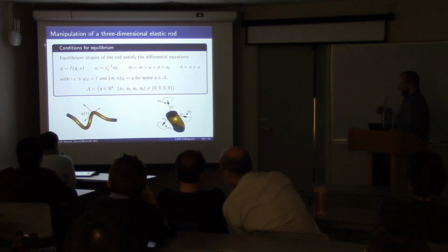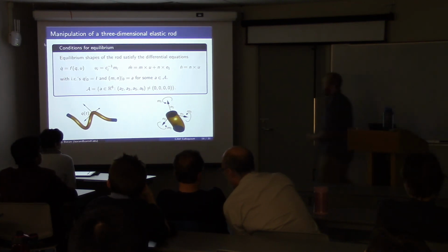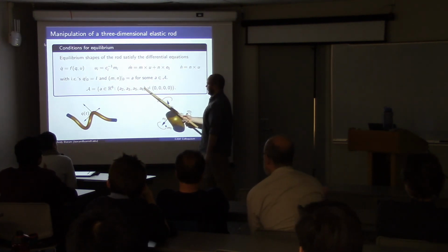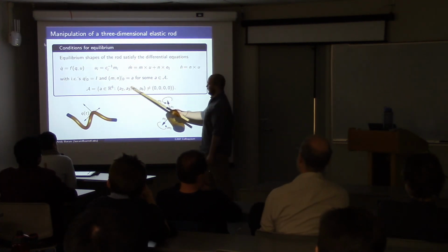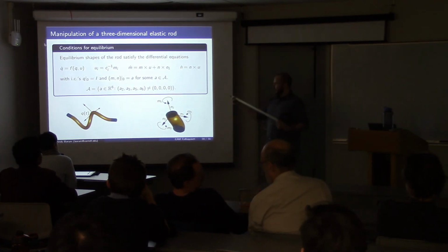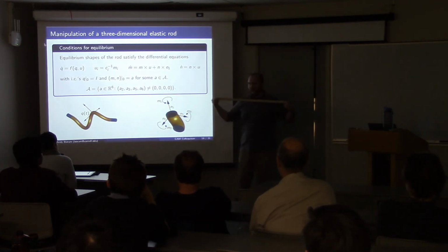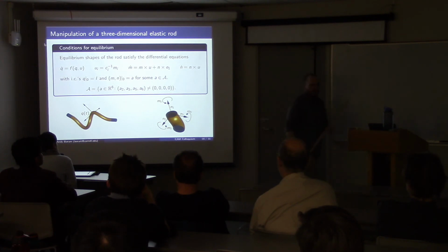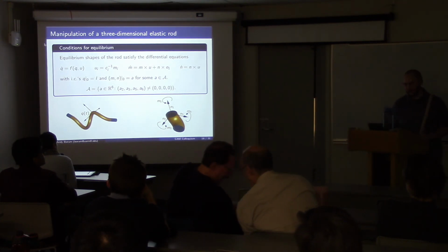And now the plane that we have to avoid has this form. It's where A2, A3, A5, and A6 are all non-zero. So the 2 shear forces and the 2 bending moments are all non-zero. The shapes in this plane have an axial force, either compression or tension, and there's a twist. Those are the abnormal shapes we want to avoid.